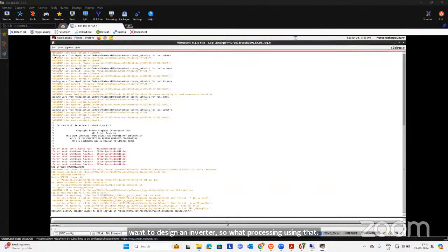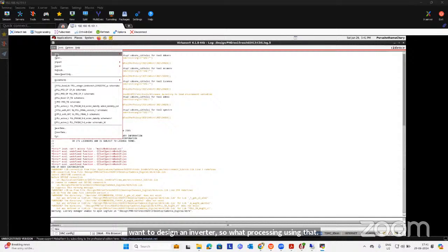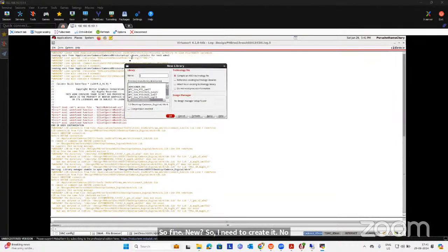File, new library. First I need to create a new library. That is nothing but technology dependent, our own inverter design. INV 29. Correct. Attach it to the existing technology library. So what is my technology library? UMC 65 LN.